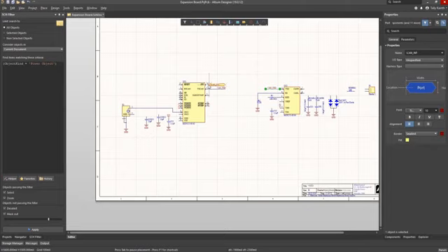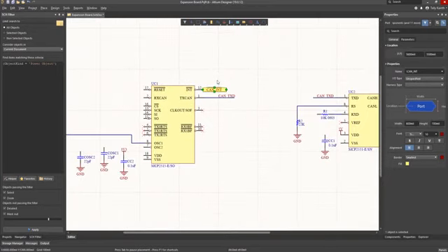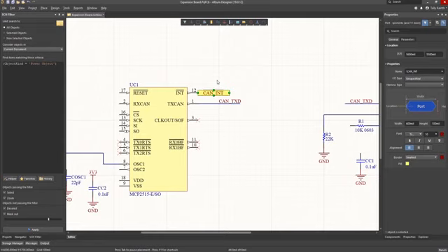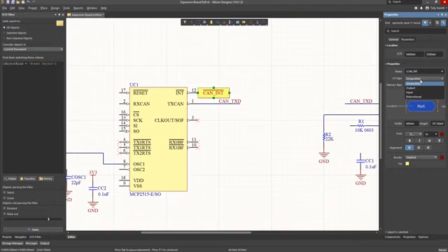When placing the port, the first click starts the port and the second click defines the length of the port symbol. Adding a single backslash to the name adds an overbar to the port name. This is enabled in the preferences under the schematics. Graphical editing enables single negation. We can resize the port to show the negation bar by clicking on one of its vertices and dragging.